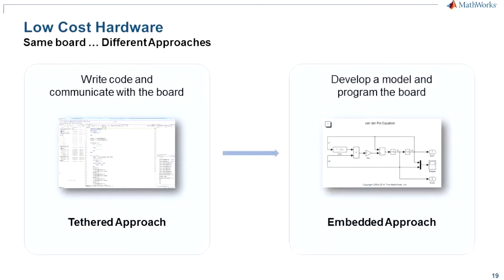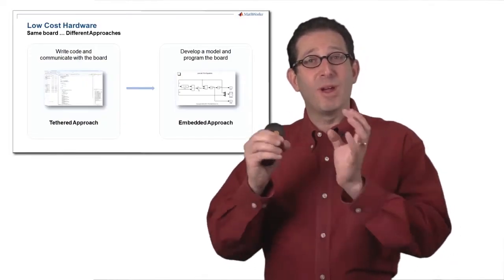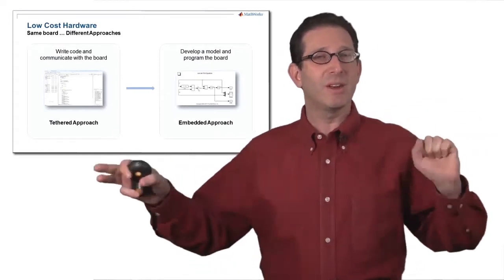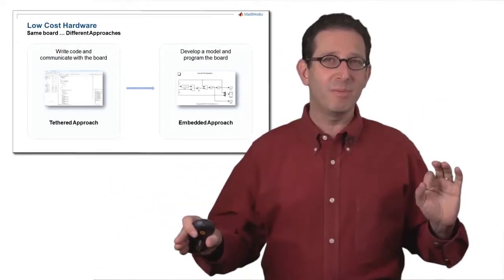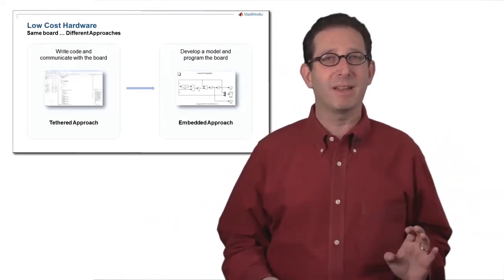The other alternative approach is an embedded approach where you can write your code in MATLAB or Simulink, and then generate code that will run embedded on the device itself, and then you can disconnect MATLAB. So this can run autonomously, doesn't need to be connected to a high-end machine that's running MATLAB.